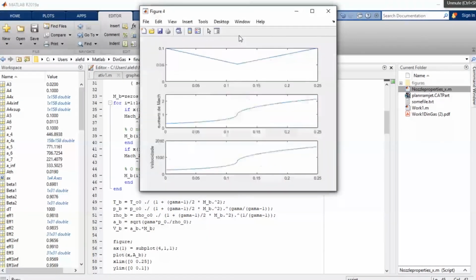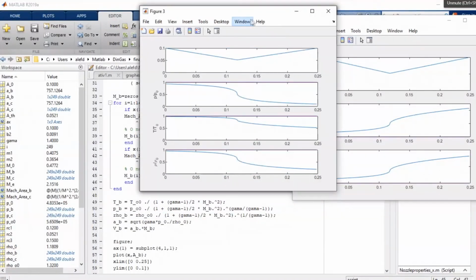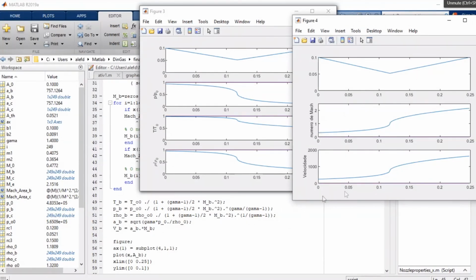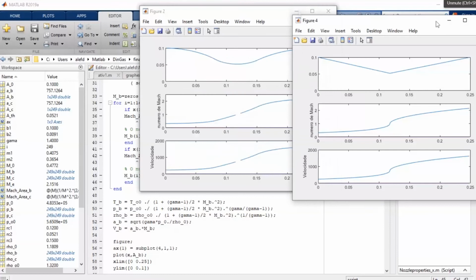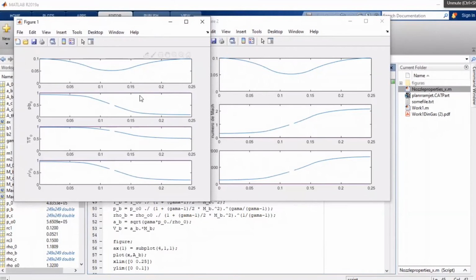And then I just plot the results, and I find the bell and the comparison one. So the conical one, I have the ratios of pressures, temperatures, and here we see, I think it makes sense. We see the value of the state quantities related to the internal pressure decreasing and the values of the numbers related to the velocity increasing. So, which for me means we are converting internal energy into kinetic energy.